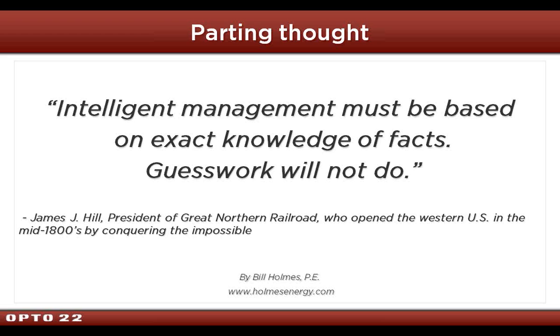Same with temperature sensors. We've been working with some big swimming pools and auditoriums, and those places don't monitor their energy separately. So rather than putting in a meter, I can put a temperature sensor on the return, whether it's water or air, and a temperature sensor on the supply, and manually plug in the CFM or the GPM, or read an amperage if it's a variable speed.